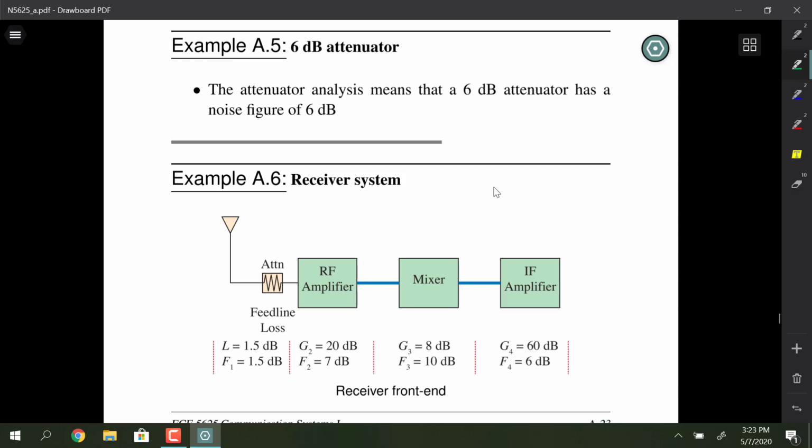And remember last time I was talking about the LaserCom system that I worked on in my first job. We put a preamp right behind the photomultiplier tube in order to reduce the noise penalty of driving over a cable. And in most satellite TV systems that you might have at your house, you'll have a preamp right at the backside of the antenna that's pointed out to the satellite, and that alleviates the noise figure penalty you would get from driving the cable directly. They also have a mixer up there too.